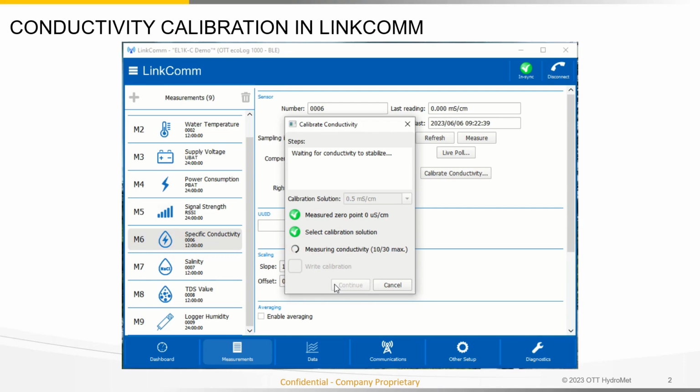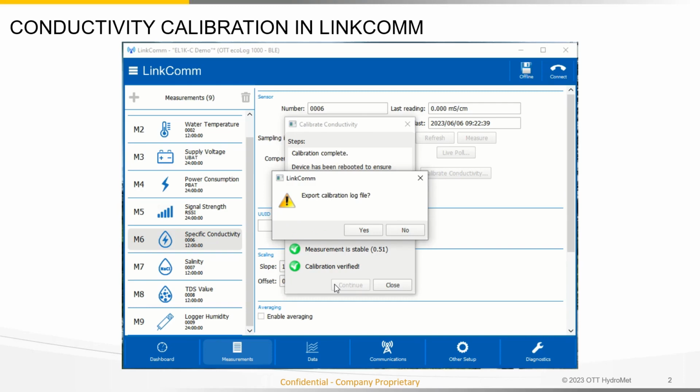Once complete, it will verify the conductivity calibration has been completed successfully, and then it will create a calibration log detailing the calibration that just took place. Once it has created the log, it will prompt and ask you if you would like to save that calibration log for future use. If you select yes, it will allow you to save the log anywhere on your computer.